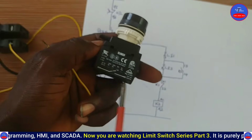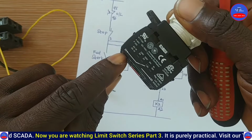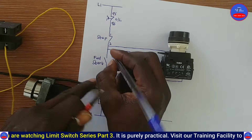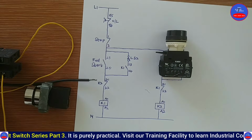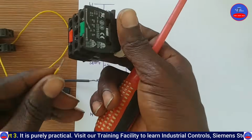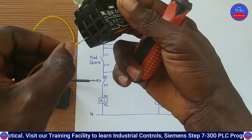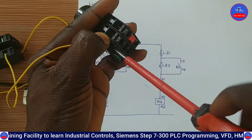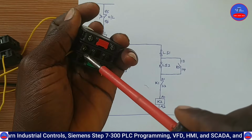Okay, this side. So you can place it anywhere. So this one is 23, 24, but they say the same thing. Okay, let me do it 23, 24. It can equally be 3 and 4. All open contacts are between 3 and 4. Close contacts are between 1 and 2. So 3 and 4, 13, 14, 23, 24, 33, 34, they are all open contacts. So just know that one.